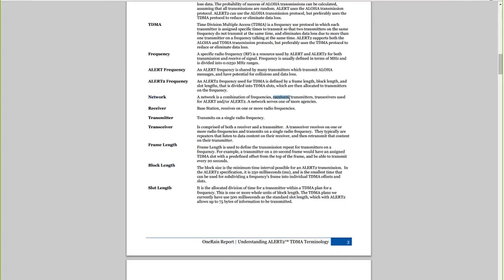So we have receivers, which are going to be your base stations, transmitters, typically your gauging sites, and then transceivers. The other term you often hear is repeaters. So these are transceivers or gauges that can listen on a specific frequency for other gauge reports, and they can pass them along on a different frequency or the same frequency, but typically a different frequency. Okay, so within each network, a network is built up of stations of one of those three types: receivers, transmitters, and transceivers.